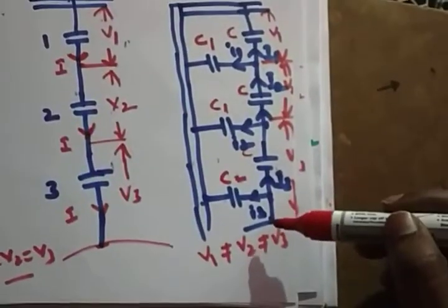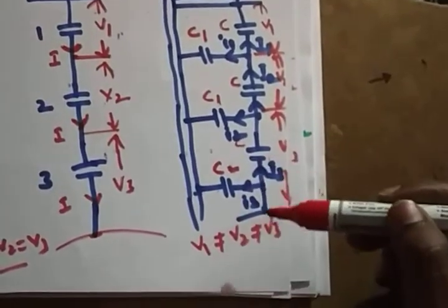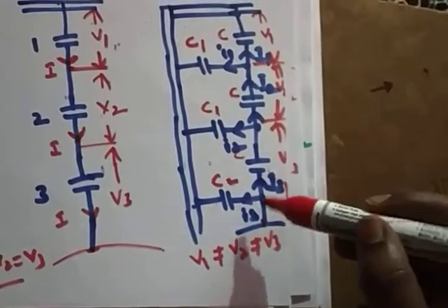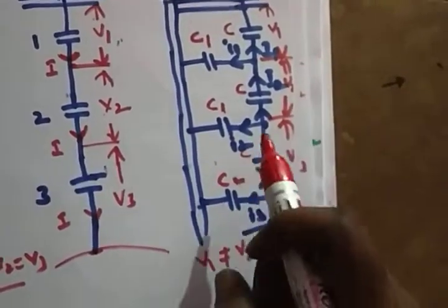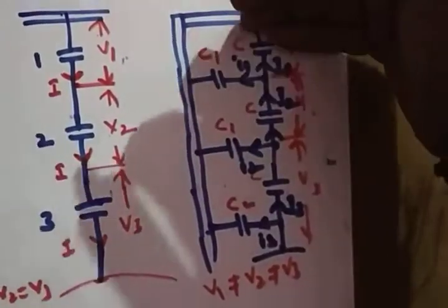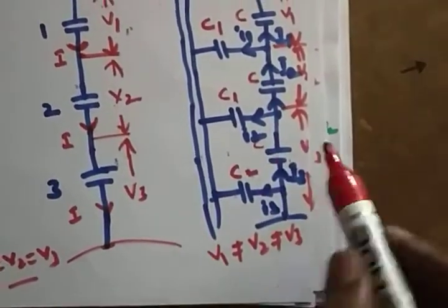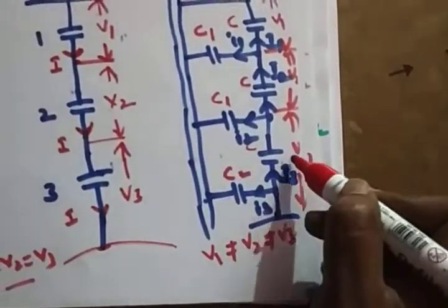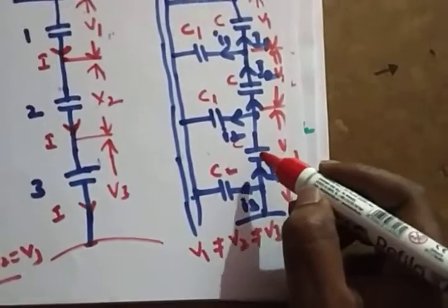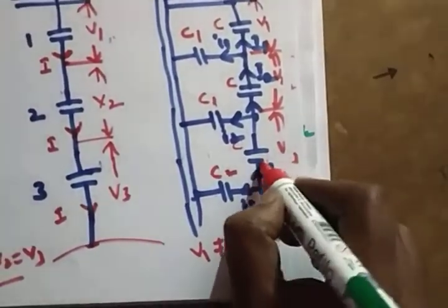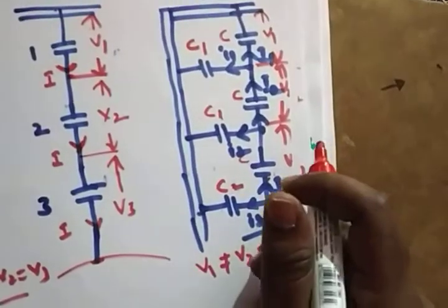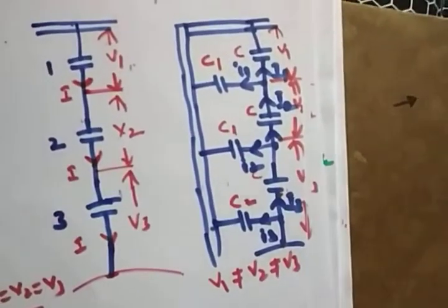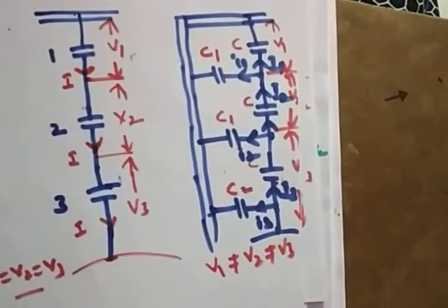The disc nearest to the conductor has the maximum stress, and going on, the voltages decrease. So the disc nearest to the conductor, having high stress, is very capable of puncture. There is a high risk of puncture at this disc. So what happens? The total suspension string will get damaged. I hope it's clear, right?